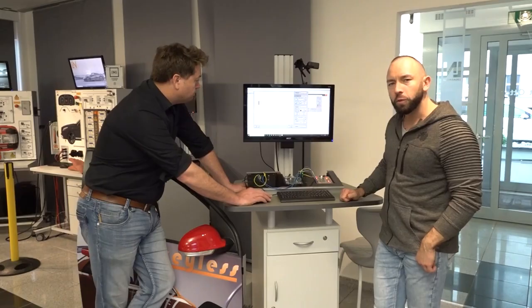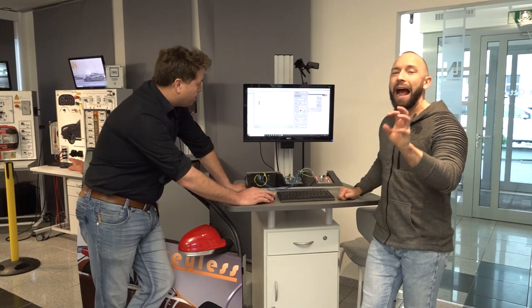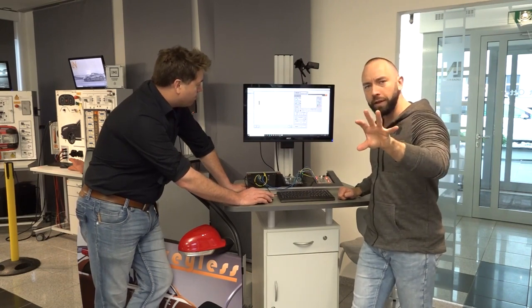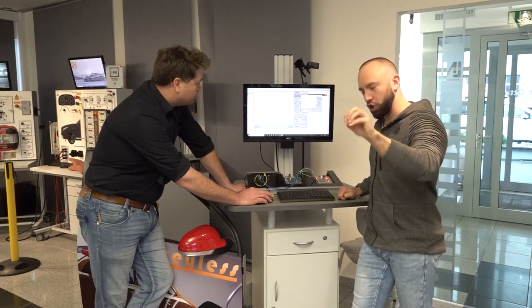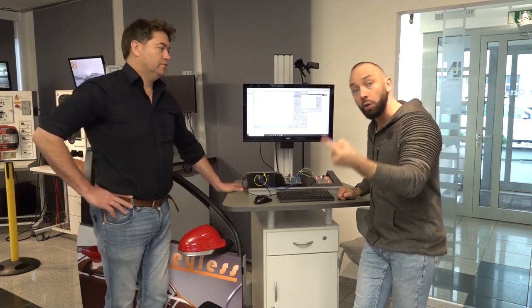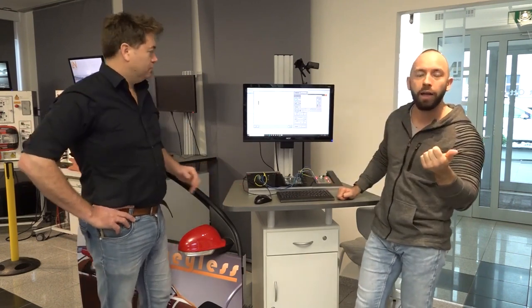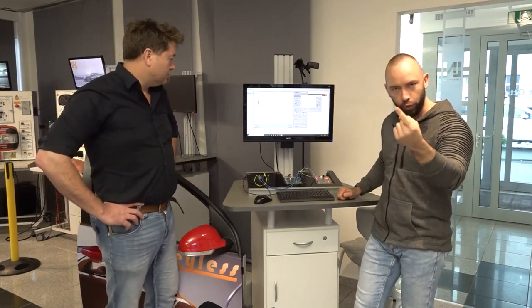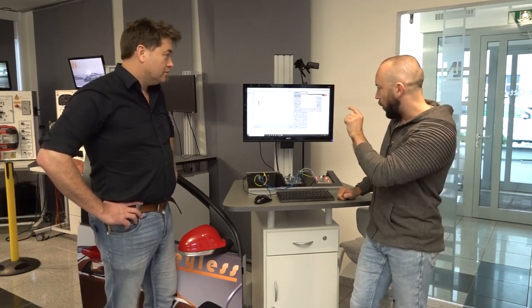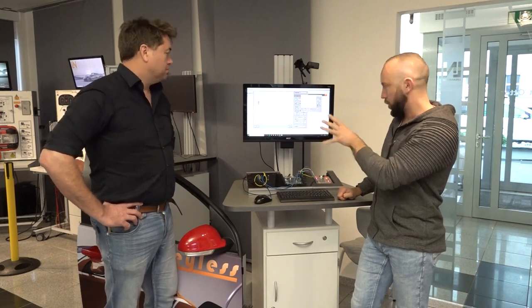And the big difference, what you see here, so we still have CAN high and low. So don't mix that up. That has nothing to do with the speed. Those are just the different channels basically at the CAN bus. So you have CAN high and CAN low at low speed, but you also have CAN high and CAN low at high speed. But what you see now, Daniel, is that the average voltage of both channels has changed.